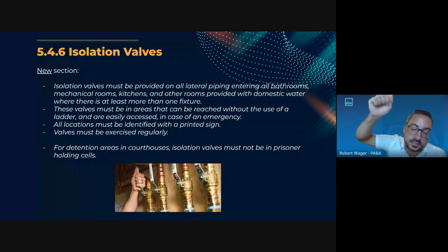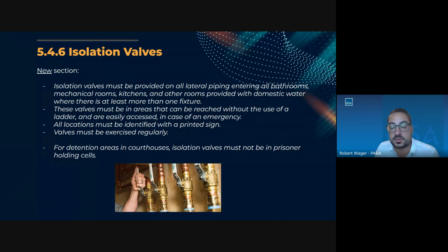Right at that branch section, there's an isolation valve. So if you're ever to isolate the whole bathroom, you have a means of doing so, and you're not just isolating locally at one or two fixtures. If there's a bigger issue upstream or a larger issue downstream and you're just trying to intercept it, you have means of appropriately isolating that.